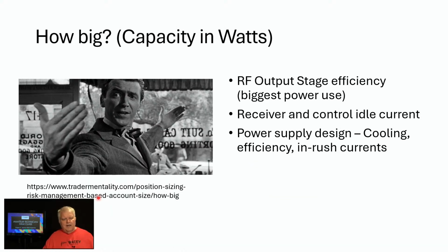Well, you need to calculate the RF output stage's efficiency. You're going to use more power in transmit than you are in receiving, and the idle currents and things like that. You need to keep up on that and to know what size generator you need.